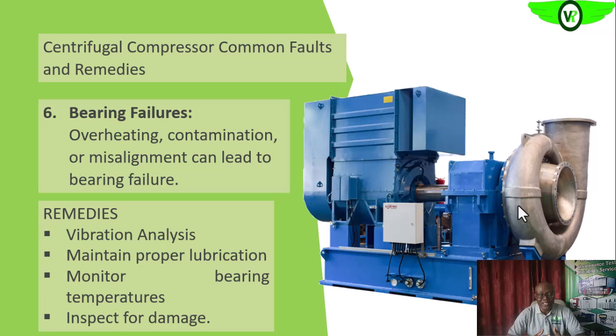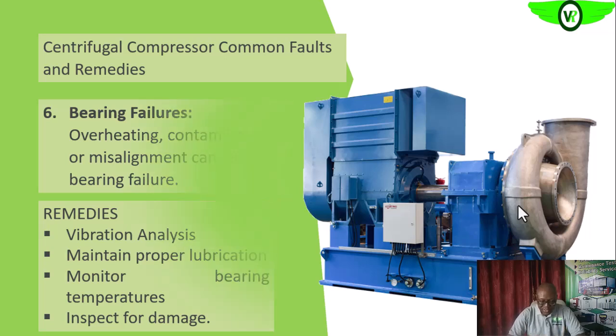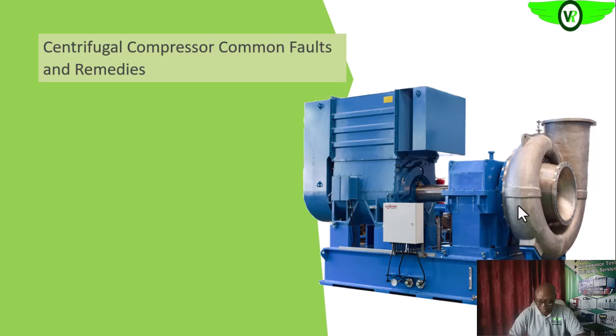Maybe our analysis took us to the bearing, and maybe the bearing is not even the cause. The problem is induced by some other component and is only reflecting on the bearing. But when we take the bearing out, we will see that the bearing is okay. That will help us determine the true cause of the increased vibration or bearing failure.